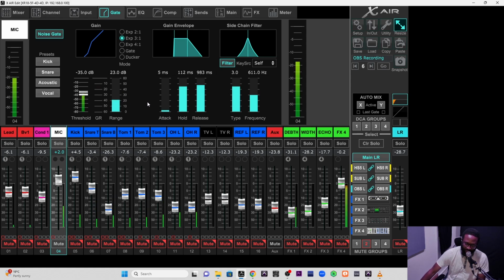So when the signal has gone past the threshold, this tells us that the gate should not work anymore for 158 milliseconds. When we release the hold, then the gate will start working again after 0.71 milliseconds. You see it more with maybe a drum. So I have a drum session here. I see something playing on there that I'm going to use to demonstrate it later on as well.